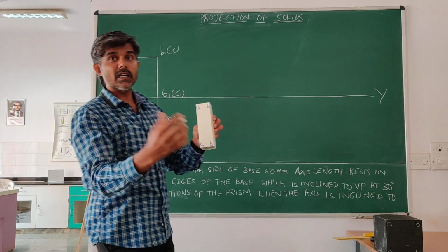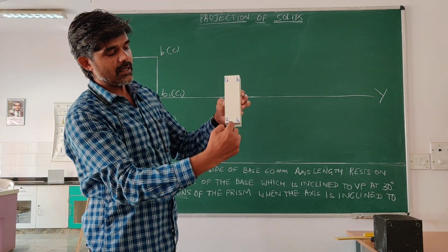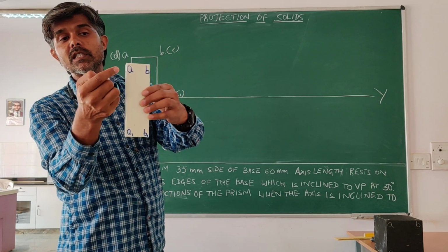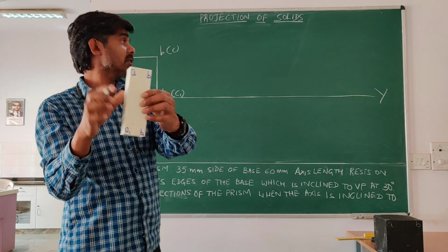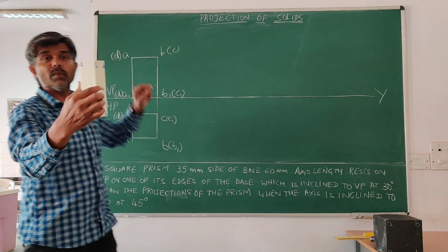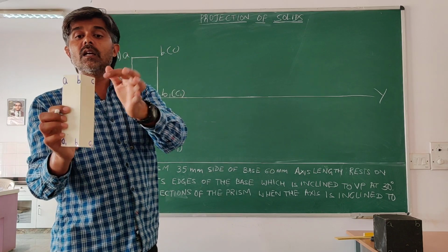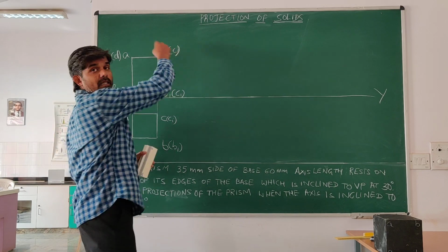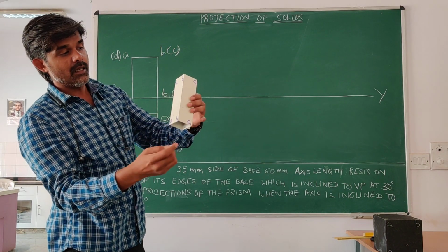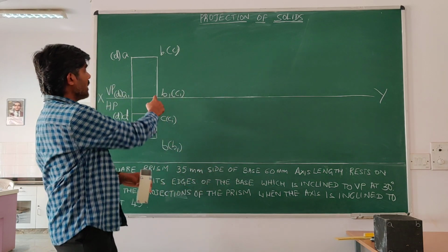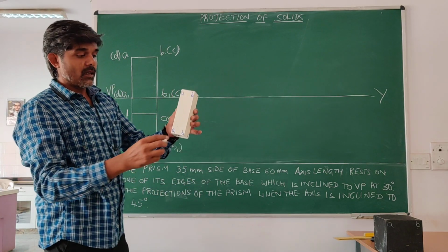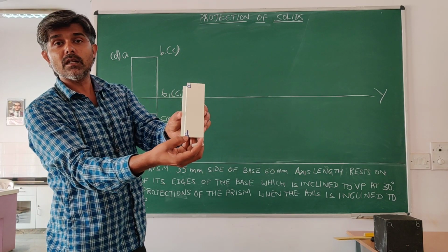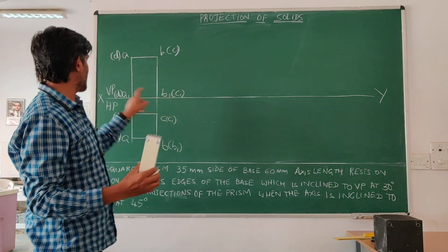I just repeat, in the front view you can see A, B, B1, A1, while we can't see D, which is behind A. So you can see A with D in bracket. You can see B, you can't see point C, so that's why I have typed C in bracket. Similarly, you can see B1, you can't see C1. That's why B1 is out of bracket, C1 in bracket. A1 is out of bracket, and D1 which is hidden is in bracket.